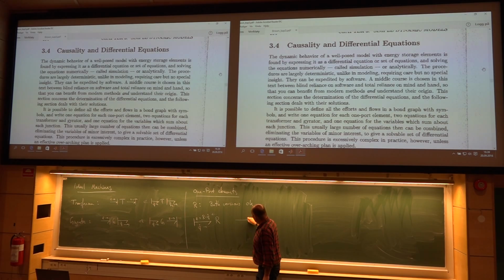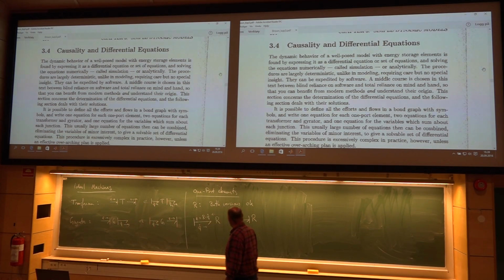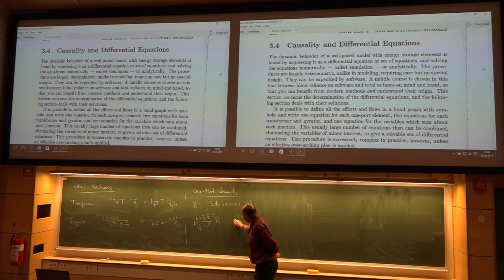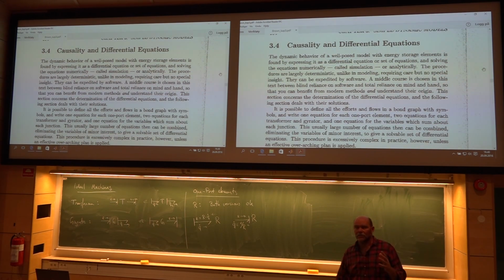If you want it the other way, resistance, and then I set the stroke here. You use of course the same equation, you just have to flip it a little bit. Now we know the effort. It's the effort that is hitting this resistance through this causal stroke, and he responds now with the flow. Q dot equals, well, fairly easy to change this equation, it's 1 over R. That's the only thing. So for a resistance, we don't mind either way. No problem there.